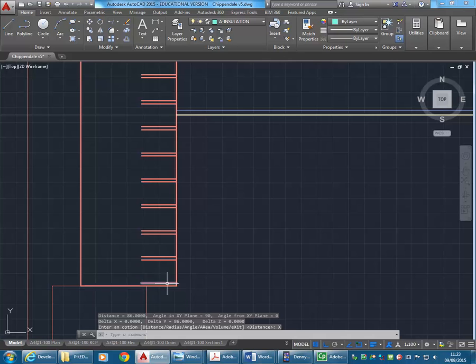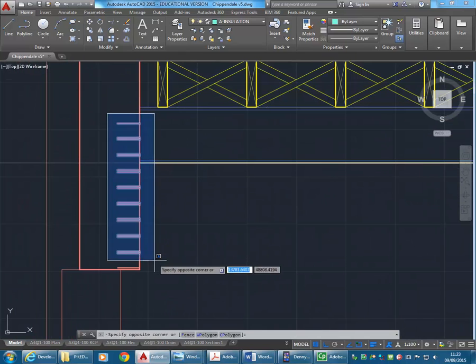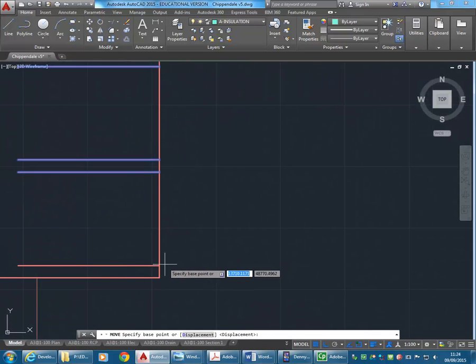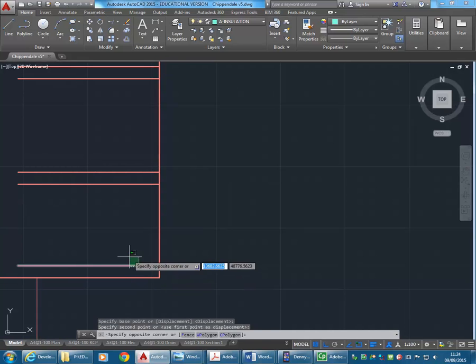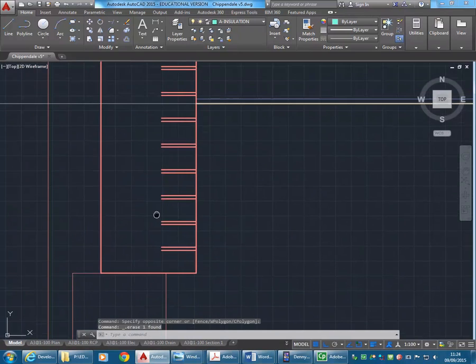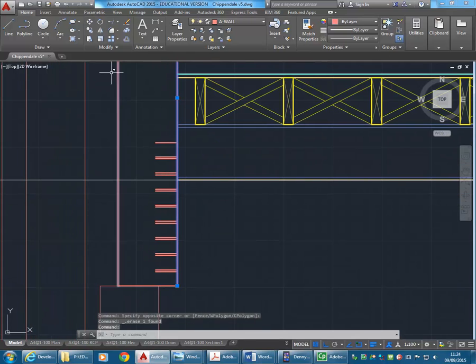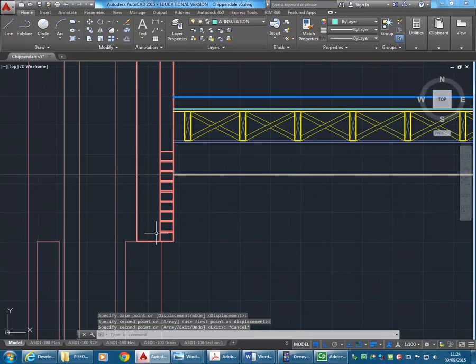Yeah, but remember we want a brick to sit on that corner exactly, so it would all come down 10mm. So I'm going to do that. So I can just snap here and then snap 10mm below, and then I can delete that line. And while I'm at it, may as well copy across the other line for the brick.